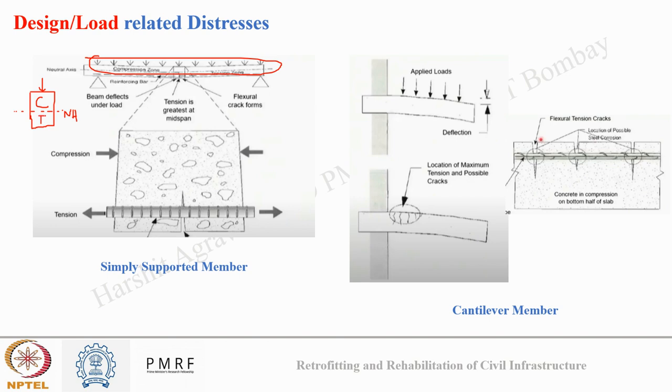Okay. Since concrete is weak in tension, we provide rebars at the bottom. So here at the bottom, we provide some rebar which can take the tensile load. Now, if there is overloading or creep, there can be cracking despite the presence of rebar. You can see here, due to overloading or creep or any other faulty design, or maybe I didn't provide as much reinforcement as was required, there is perpendicular cracking that has happened due to the loading